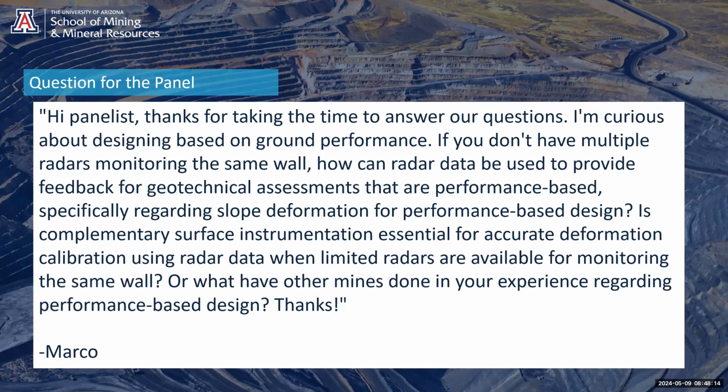One thing to be very mindful about is that ground-based radars are typically inside the pit, or at the crest of the pit. There was a rock mass there, somebody excavated it, so the natural reaction is that it will try to close. Radars use, with different techniques, the surface inside the pit that is deforming itself as a reference for atmospheric correction in order to detect other areas of movement.